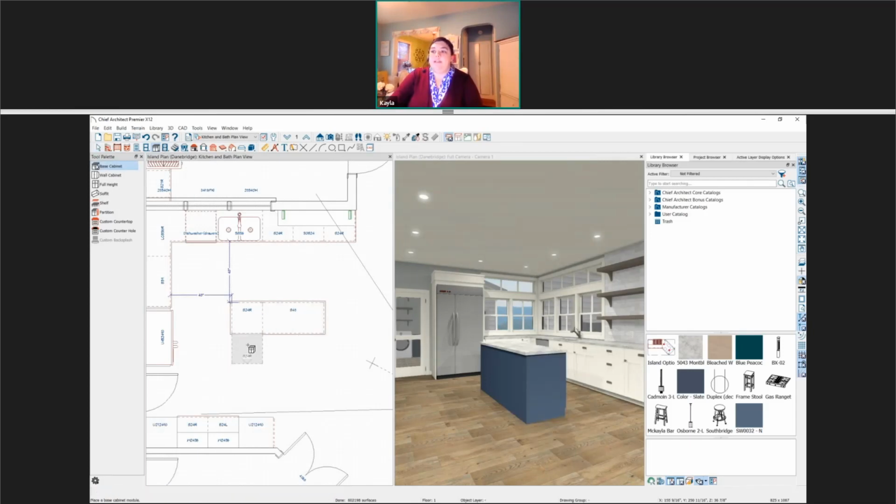And then I'm going to place another cabinet in the back here that we're going to change to a bookshelf. So I'll just place it and then I'll redimension it, then we'll open it up to edit it. So I'm going to resize it to 18 inches deep and 72 inches wide. Nice big bookshelf area. Then we'll open this up.